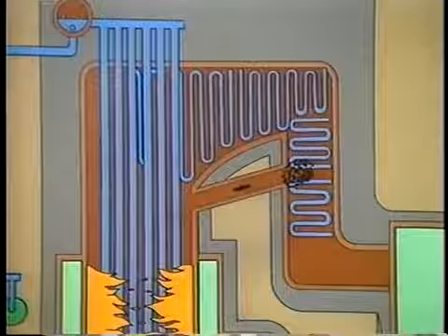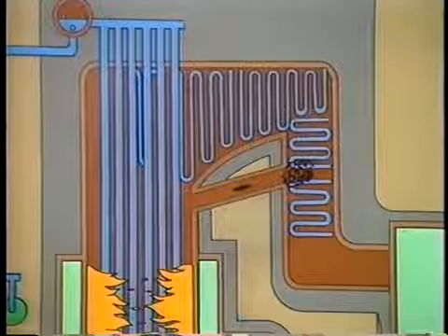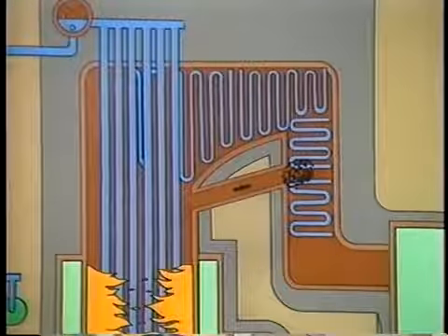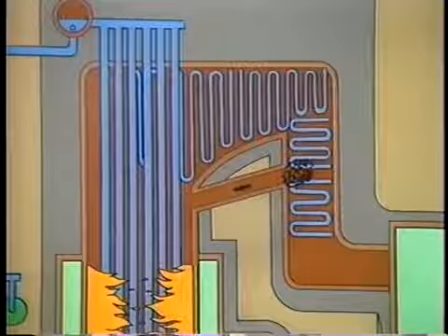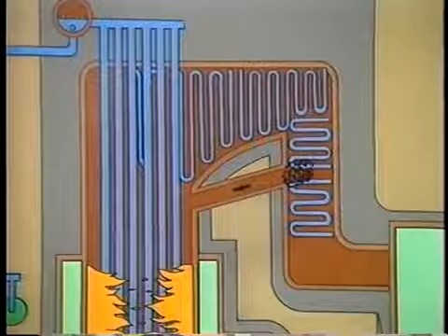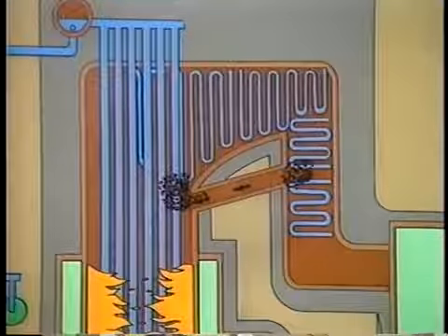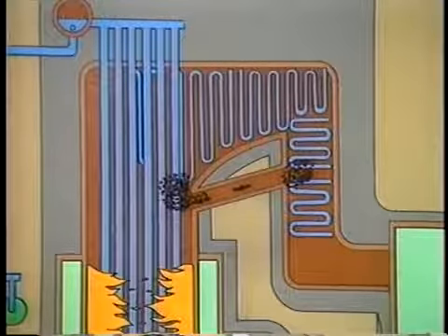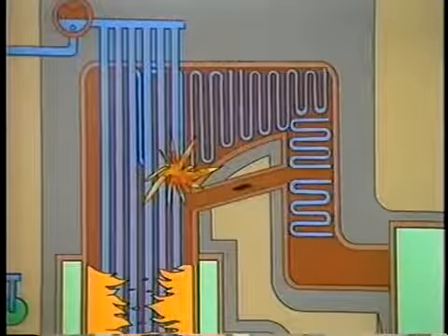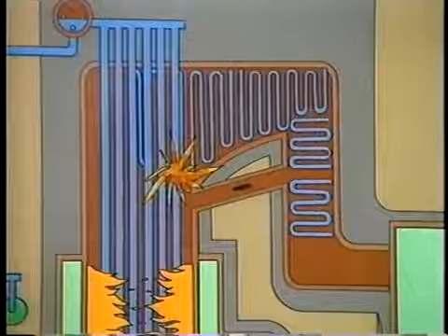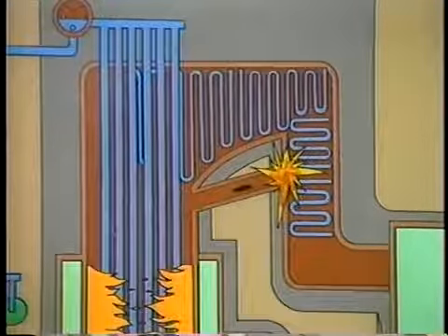The combustibles that have accumulated in the ductwork are no longer in a dead spot. They are immediately reintroduced into the flow path of flue gas going to the economizer, or, due to some back pressure around the damper, are forced back into the furnace area of the boiler. The result could be sudden and uncontrolled combustion. In other words, an explosion in either the furnace area, the ductwork, or near the economizer.